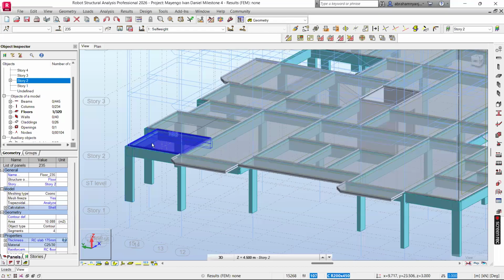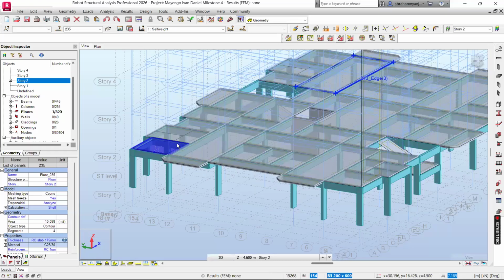Now, if you follow that, you're sure that all the slabs that you have placed on this floor, you have been placing them at the grid intersection where you earlier placed the columns. That would be your only check as you're modeling, because from there onwards, if you pressed them at the grid intersection, it will be at the grid intersection.